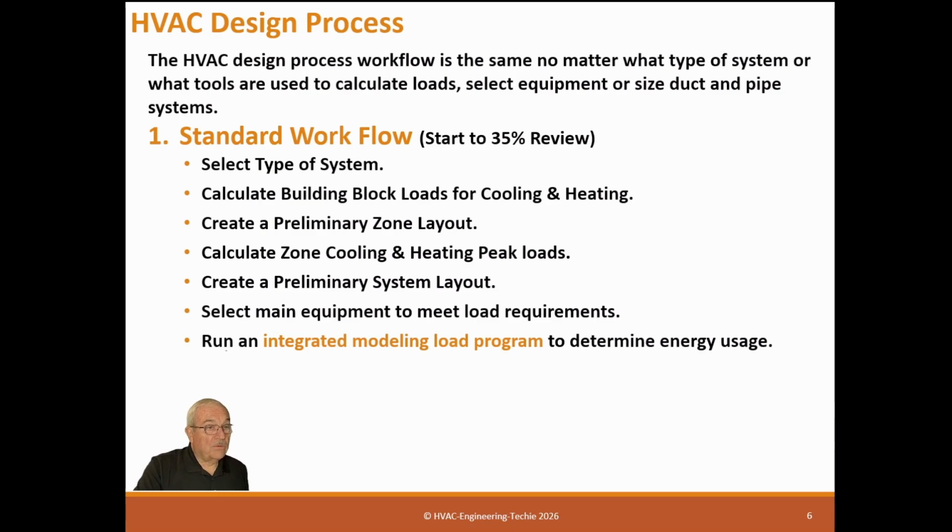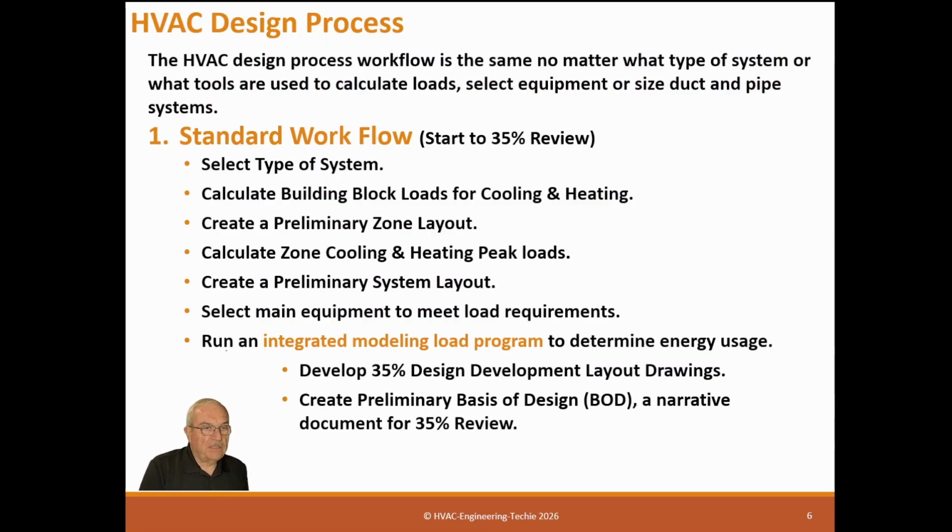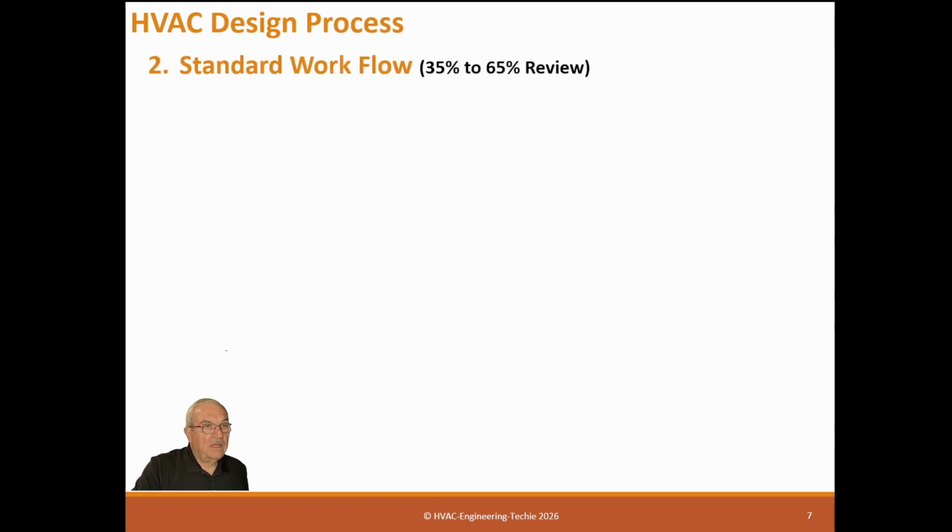And this will happen, of course, if you have a green building or if you have an owner that requires this. Develop 35% design development layout drawings, which are simple drawings. The architect gives you background drawings for 35%, and all the major equipment is located, and you may show duct and pipe layout single line, just rough sketches of what's going to happen. Create a preliminary basis of design document, a BOD, a narrative document for the 35% review, and we will go through what that is.